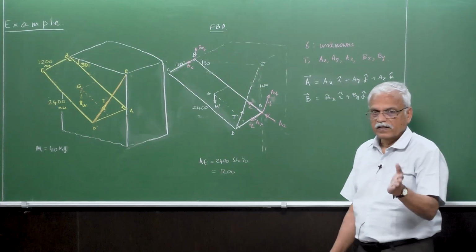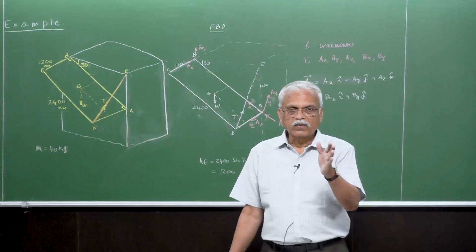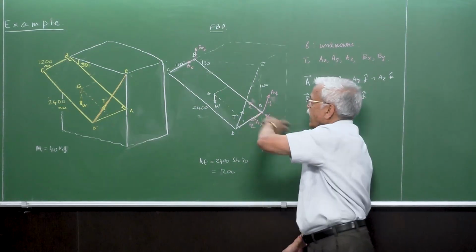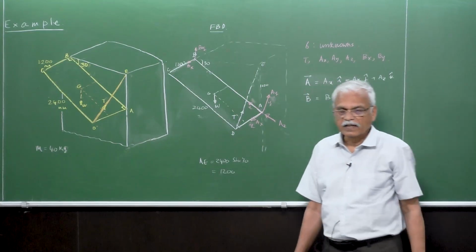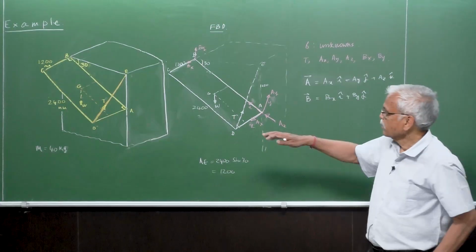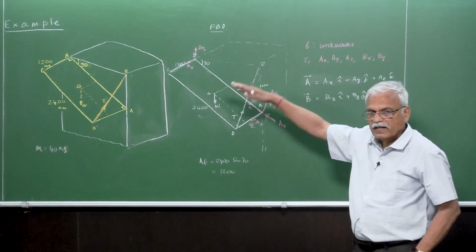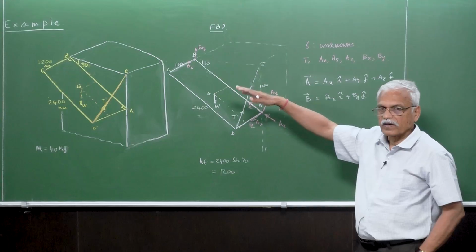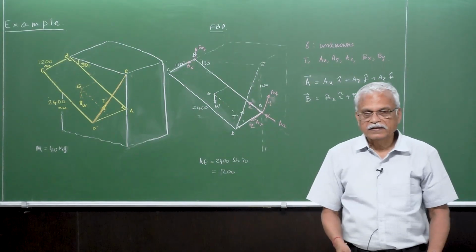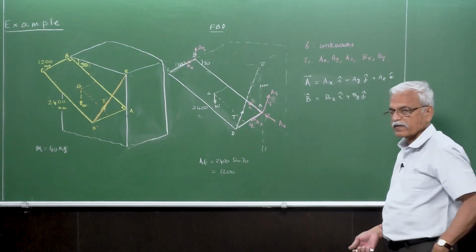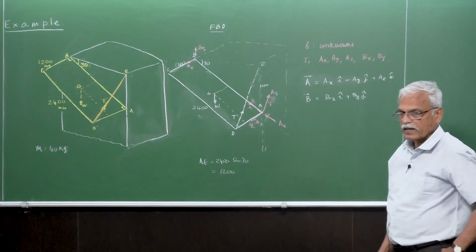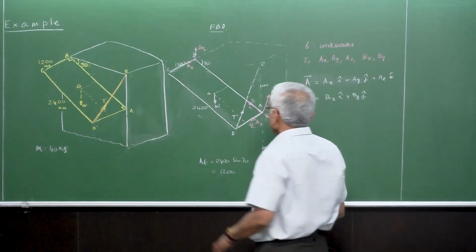So that the door is completely under equilibrium about this Z axis, about this AB line. It has a tendency to rotate, but its moment about the Z axis is 0, so then it's under equilibrium. So that is why the AB has been taken.